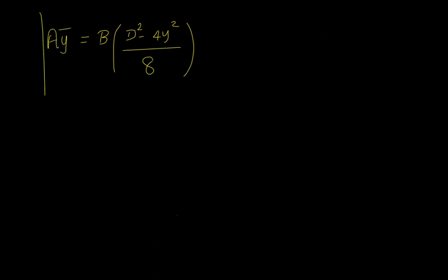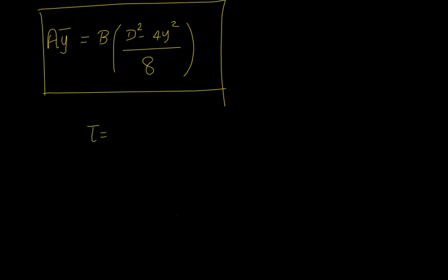All I'm going to do is take this value and plug it in the expression for shear stress. So the expression for shear stress is tau is equal to F into a into y bar. Instead of a into y bar, I'm just going to plug this expression. It is capital B by 8 into capital D squared minus 4y squared. That is a into y bar, whole divided by I into the breadth, which is given by capital B, breadth of that particular layer that is under investigation.